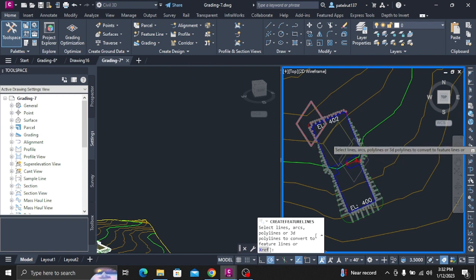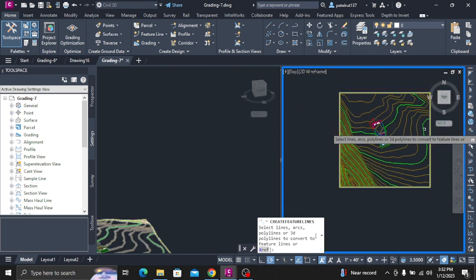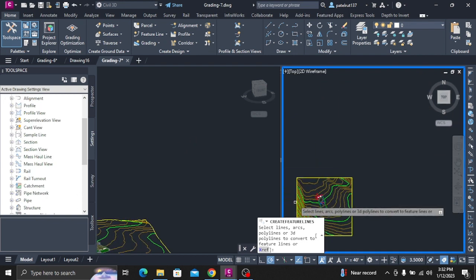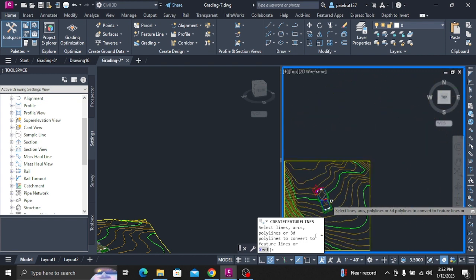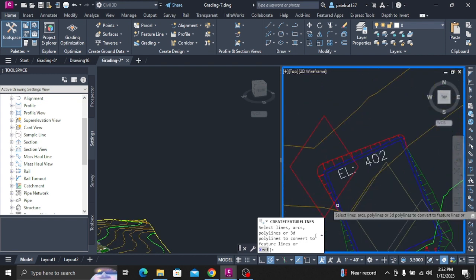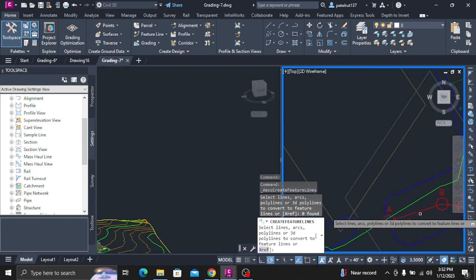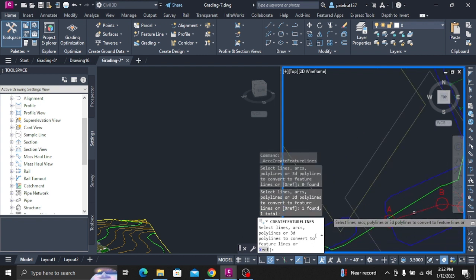As you see in the following image, the new common feature line elevation affected the infill gradings of both the ramp and gray infill area. When two feature lines share a vertex, the elevation of both feature lines at that vertex is determined by whichever of the feature lines was most recently edited.